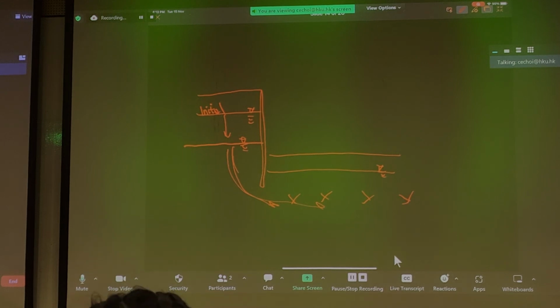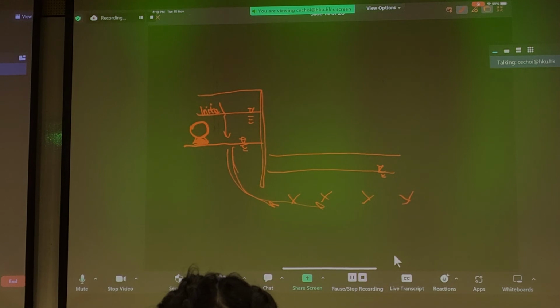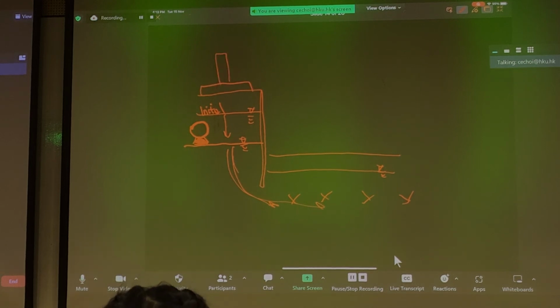And if you remember from our consolidation lecture, this causes consolidation, and it can cause settlement of infrastructure outside. If you have, let's say this is a gas main that's sitting on some sort of footing inside the ground, you can cause the mains to dislocate, right? So the pipes are connected by joints. So if you have localized settlement, then you have dislocation of utilities. If you have infrastructure at the surface on some sort of footing, this can also cause settlement around your construction site. So dewatering requires you to calculate the subsidence from drawdown.